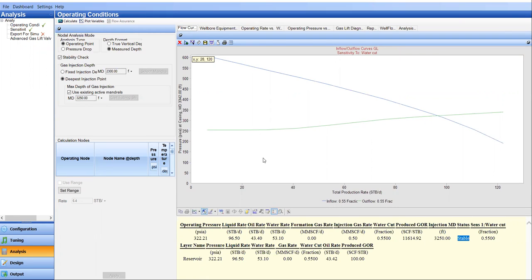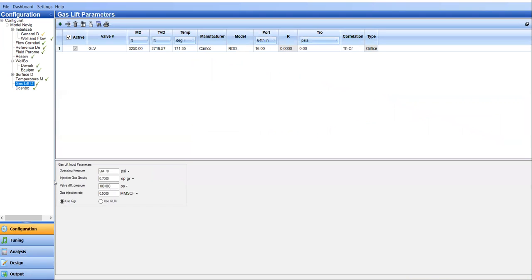Okay, so we already designed the gas lift, we input the configuration for the orifice valve, the location, the size, the correlation that you use, you input it here, and then you run just like usual. In WellFlo, you create the nodal analysis and you get the result. Hopefully in the future we can also design the complete gas lift, from the loading valves at the top and then at the middle, and lastly at the bottom you set the orifice valve. But I think here we can stop.